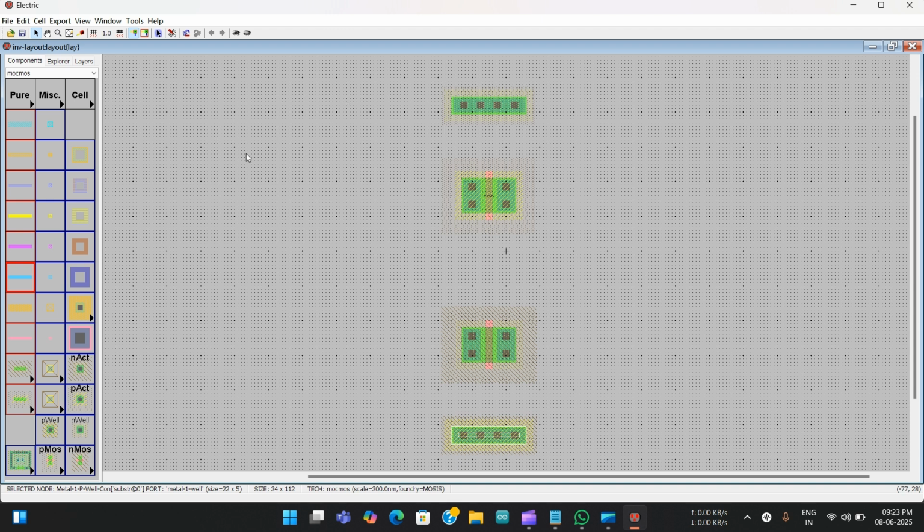According to the inverter connection, if you compare it with the schematic, the first terminal is connected to the source part, right? So before that, we should be doing the drain to drain connection here. So I'll do it. Click here, left, right. So this is one connection, and then both the gate connections, that is the input. In order to take the common input, we connect both the gates of the transistors, and we take a common output. So do that as well, left and right.